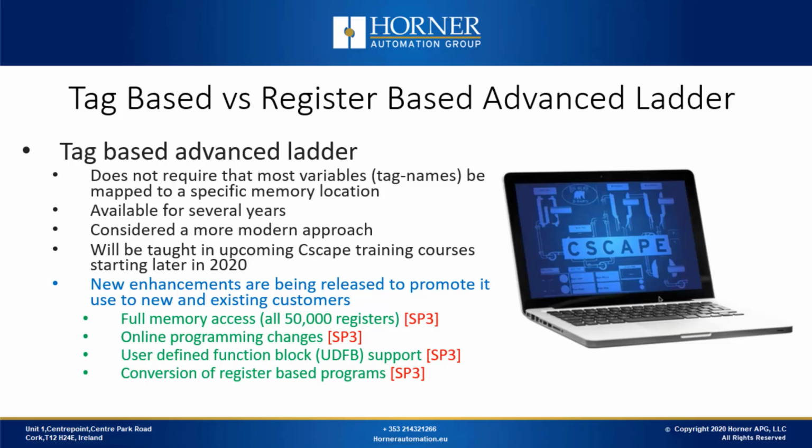The tag-based approach is certainly considered the more modern approach. There are also several new enhancements being released that should promote the use of tag-based logic. First of all, we're eliminating the restriction on the number of registers, as with register-based logic, you're capped at 10,000 registers, but with tag-based, you can now use up to 50,000. So with the introduction of Service Pack 3, you'll have full memory access.